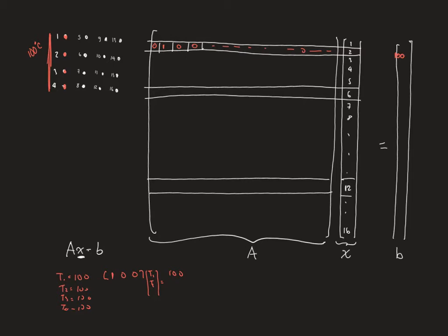Now let's apply the actual equation to the inner nodes. So again, every node has an equation, and the inner nodes are the ones that have the equation that we want to solve, which is the heat equation. The other nodes, the boundary, have the equations of the boundaries, so the boundary conditions. I will not tell you this one. In this exercise, if you remember, this is going to be Neumann, this is going to be Robin, this is going to be Robin as well.